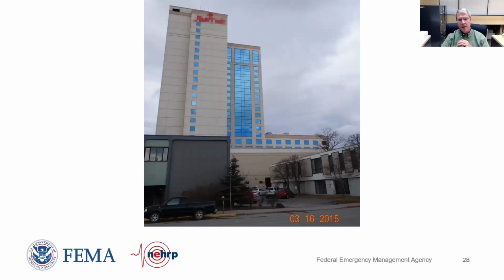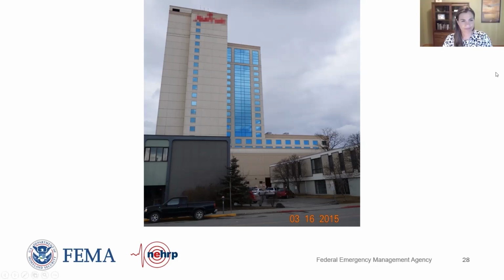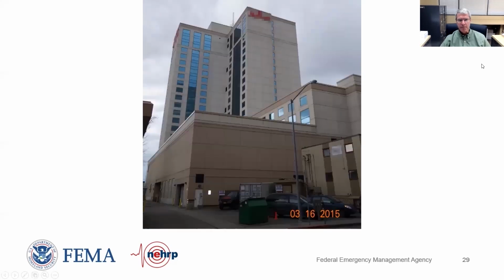So we have, again, around the side of the building, some very large areas with no windows, so we can put structural elements in for a lateral system. It's kind of a good sign. So if it was a moment frame, there might be a lot of windows. Correct. And so here's kind of the backside, and we see evidence of that again, where we've got some pretty large areas of no windows, no penetrations, and it's vertically stacked very nicely.